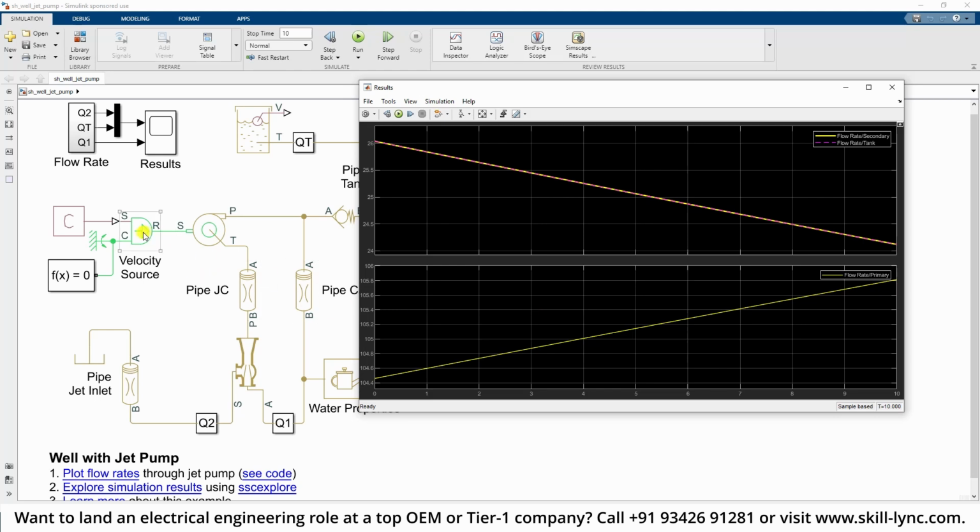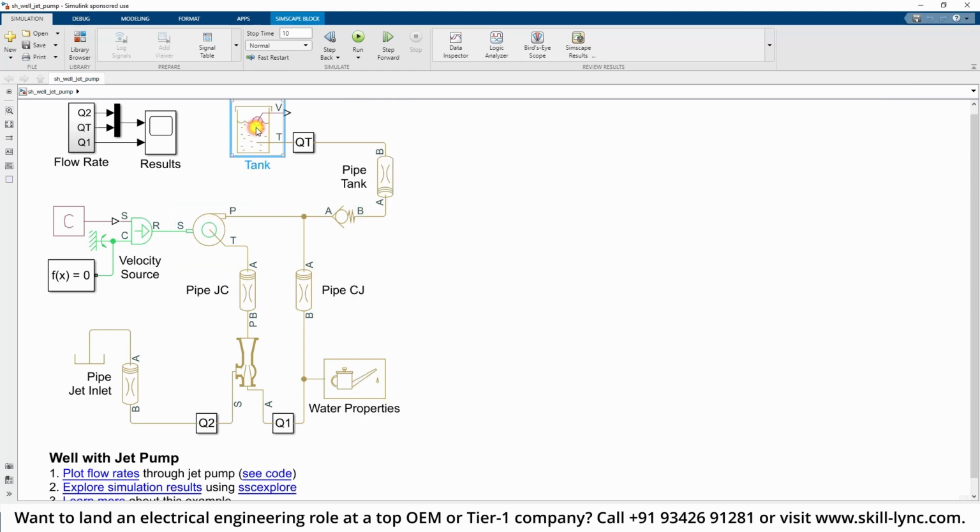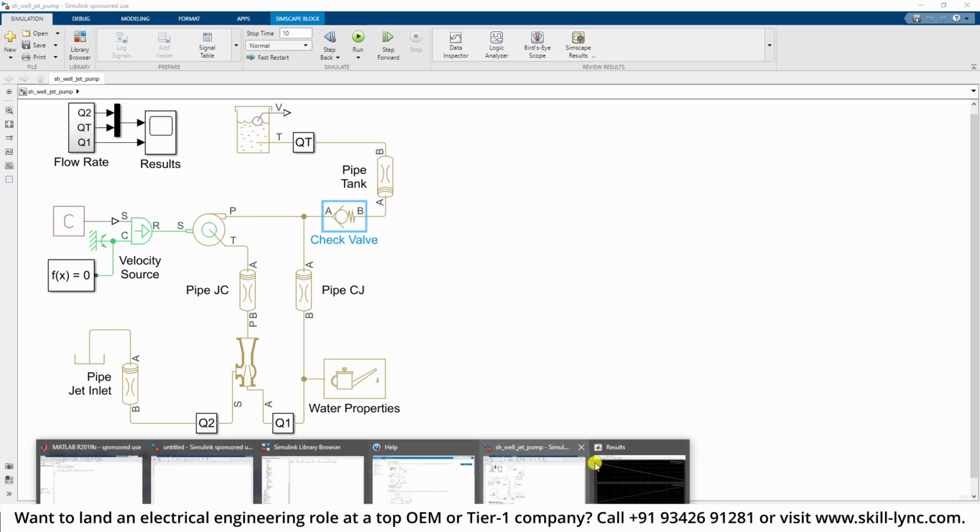Now if you give a different angular velocity, instead of 1800 rpm, say 1000 rpm, and the remaining parameters are all the same, you will get maybe a different flow rate, right? And if you change the pump related configuration, or the tank related configuration, or the pipe and valve related configuration, then all those changes will result in a changed output.